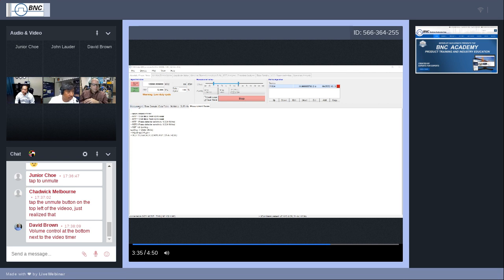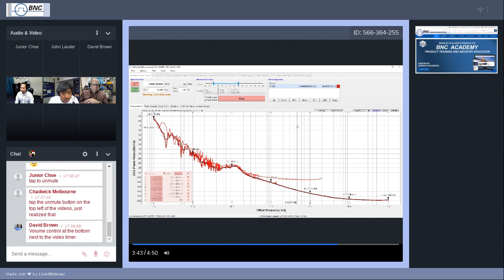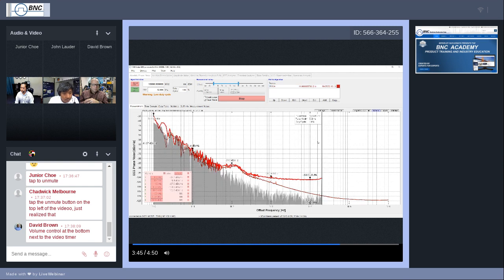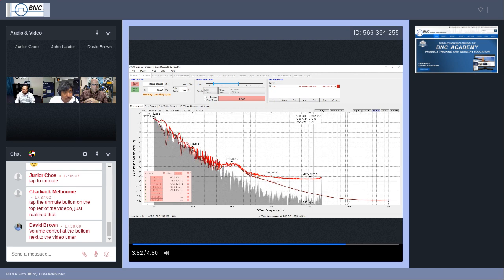And if you switch to the measurement tab, you'll see the partially correlated pulse measurement. Click on select. It also detects the pulse width, duty cycle, and the pulse rate. Also in pulse mode, the maximum offset you can see is the pulse repetition rate. In our case, it is 20 kilohertz.